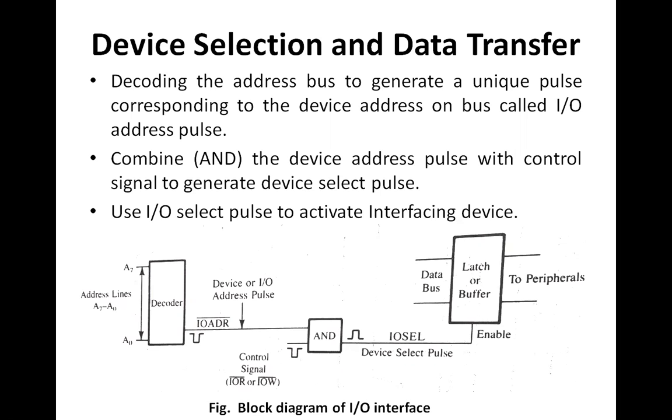Now the answer to both these questions can be arranged in the M3 machine cycle, and the latch will be enabled only when the input output memory signal becomes high, as well as the write signal becomes active low. Similarly, the address of an output port is also on the address bus during the third machine cycle, that is M3.